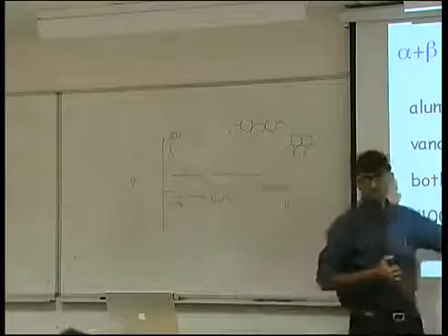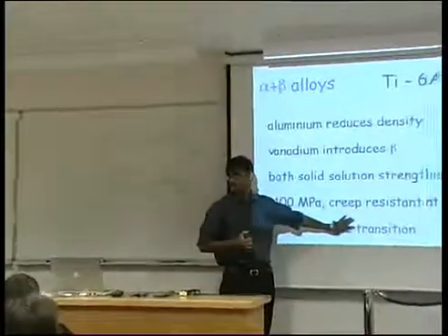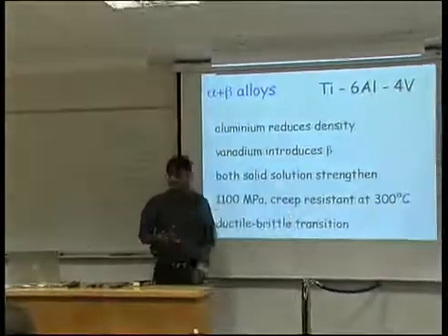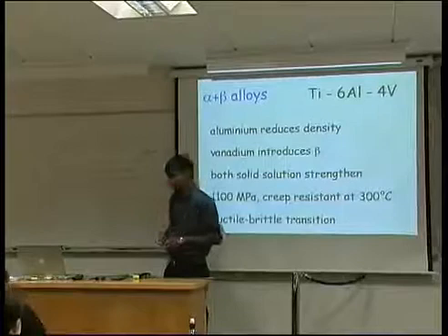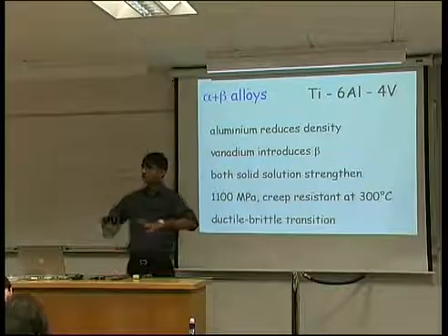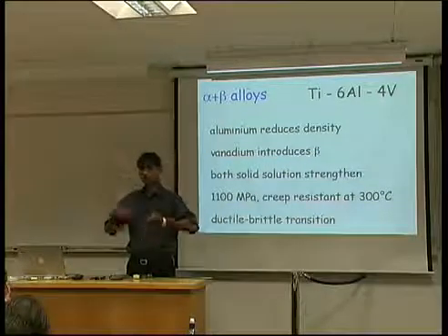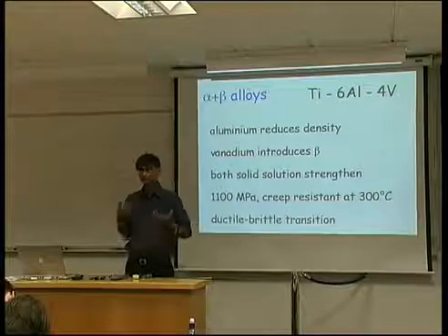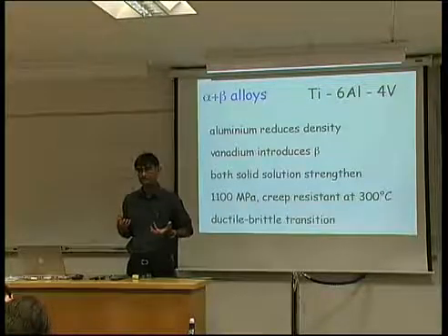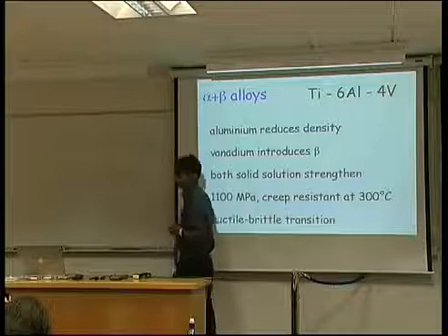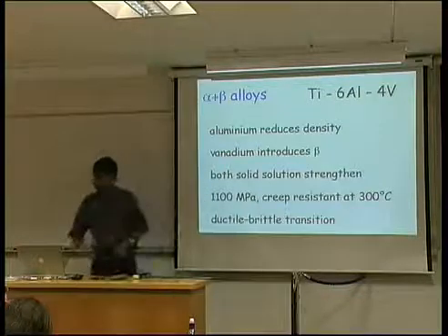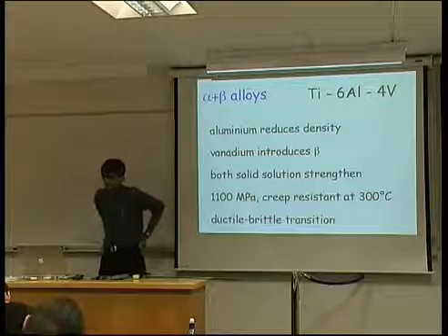So the fact that we have quite a lot of body-centered cubic phase in this alloy, and the fact that it is very strong, unfortunately means that its ductile brittle transition temperature is above room temperature, so it fails in a brittle manner. Without much ductility.